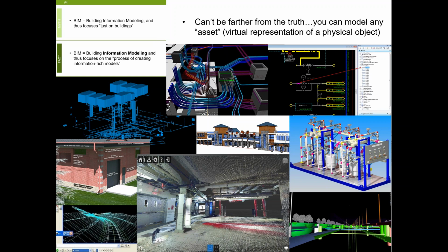Can SketchUp be used for BIM? Yeah, that's why I put that in there. It's been my biggest struggle. For years I've said no, and then all of a sudden SketchUp built IFC compatibility. So it's a struggle because I can go SketchUp to an IFC file, and by definition of getting to an IFC, I have delineation of walls, doors, and windows and stuff like that. So I cringe. It'll get better. I think it will, because they're smart, right? They know if they kept it as a sketch, it would fail, right?